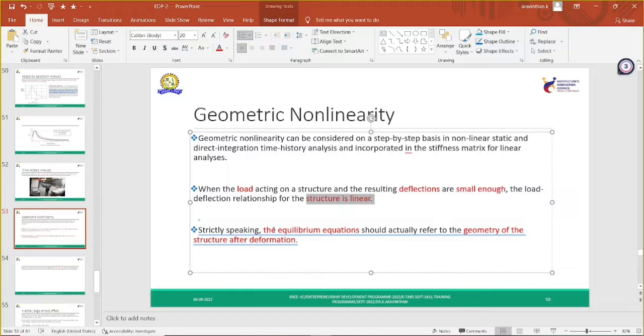Generally we are building a number of stories, 10 stories or 5 stories. On all the stories you have floor load, and at each and every floor you will have dead weight. The column is a cantilever which is fixed at the ground and free at the top. All the columns have only one type of support, fixed at one end and free at the other end.